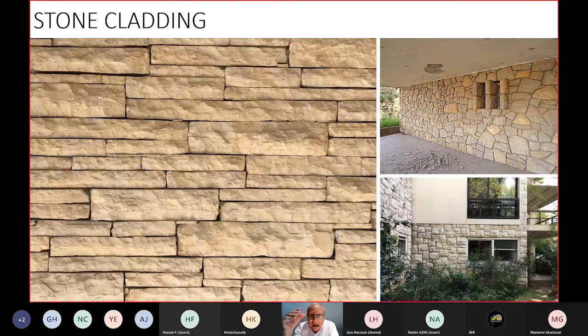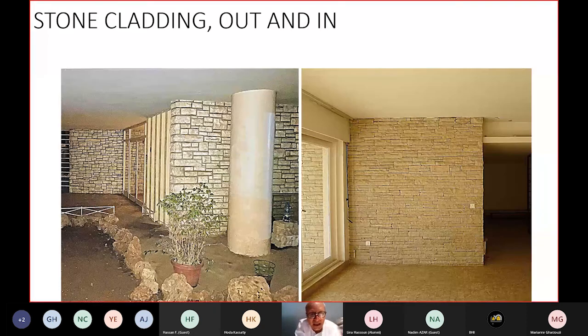So the stones, as you can see, are not necessarily built as bearing walls. They're not bearing walls. They're actually a play of material. The stone is here used just to express a texture to the wall, and it's no longer something that is holding the building. It's not structural, it's just aesthetical, although many times it was still used at the ground floor because it's still heavy. As you can see here, for instance, on these ground floors, but the stone is just a plane in the air. It's no longer a box.